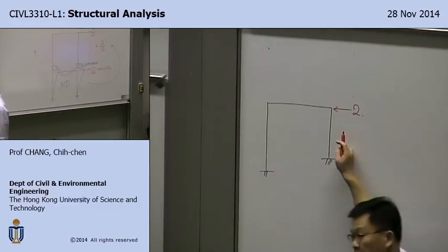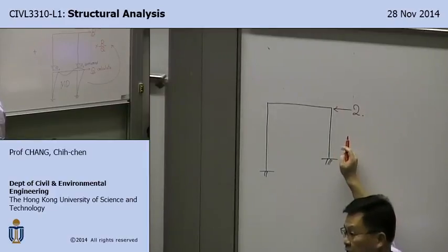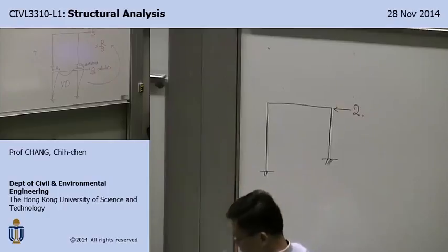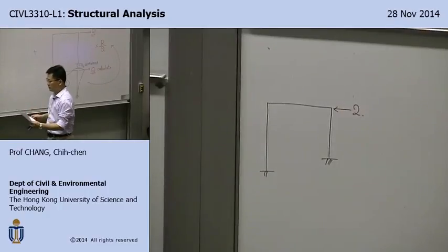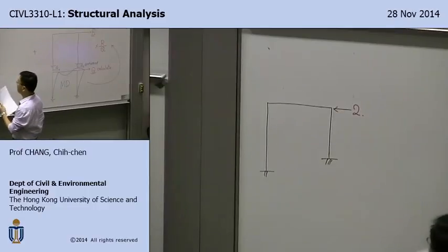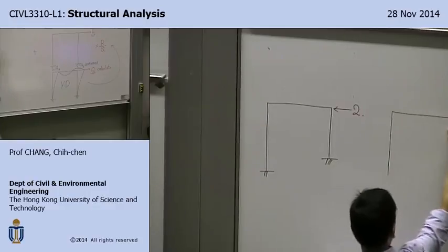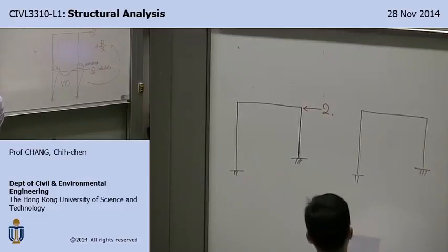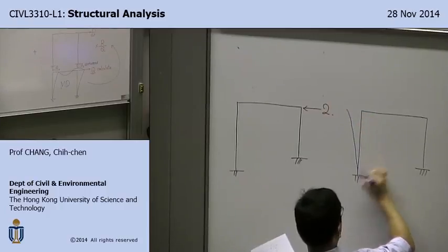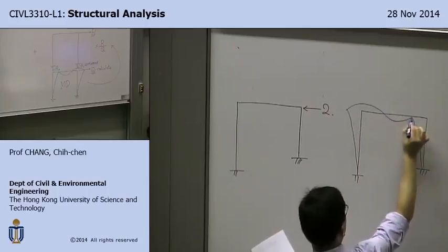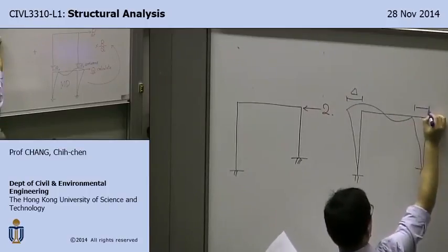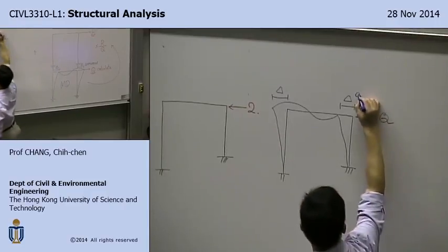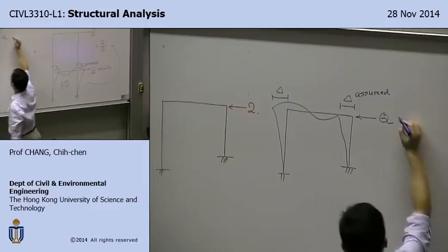All right, so I need to calculate this case now. But instead of directly calculating that, which is difficult by moment distributions, because I know that it's going to be pushed that way, the translation is unknown. So instead of that, I'm going to assume this and get that.